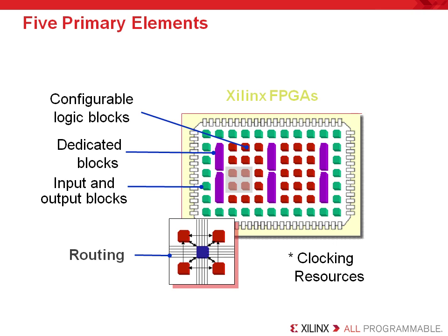It is also designed to assure short routing delays so that system performance objectives can be obtained. To aid the software in the effort of obtaining desired performance, Xilinx supports the use of timing constraints through its ISE design suite. Timing constraints allow designers to specify their desired timing objectives, which the tools will then use to guide the placement of logic and the assignment of routing.